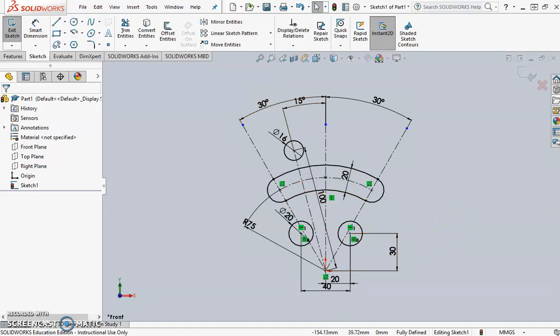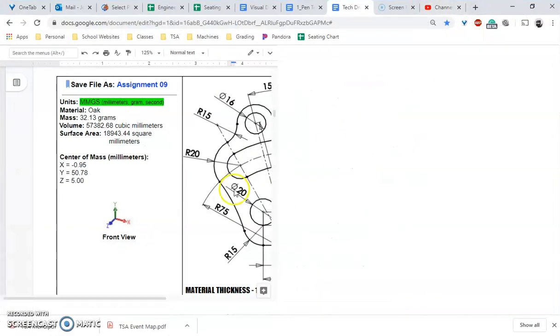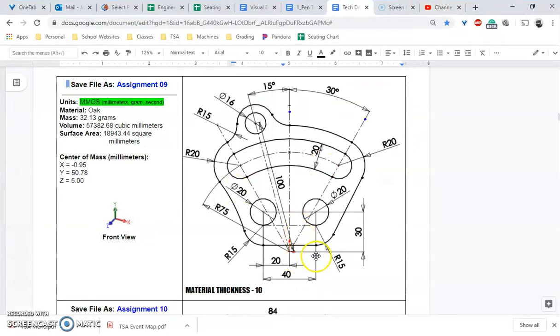So you're going to see on this, if you sit back and look close a little bit before you just start drawing, if you look at some of these, you can see that all the ones with a radius actually have a defined center point. So this one has a center point, starts right here, it connects to the construction line, and it wraps over, and it's actually coincident with that construction line.